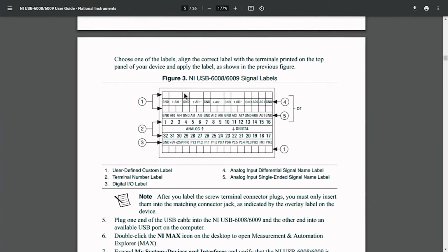In case we are using single-ended data, the negative terminal can be directly connected to the ground. In order to eliminate noise and avoid ground loops, it has been provided with multiple grounds after each differential channel, so that the terminal pin can be directly connected to the ground.